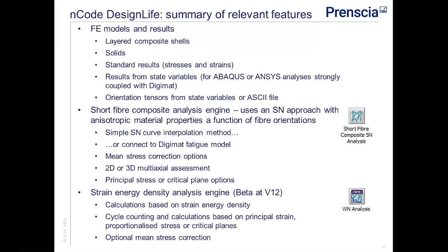We also work quite closely with Digimat, so that if you run an Abaqus or ANSYS analysis which has been strongly coupled with Digimat, one of the ways it can write the results out is, rather than the normal stress and strain data sets, as state variables, so we can read the stresses and strains from there as well. The other piece of information we need from the model is the orientation tensor information at each of the calculation points.